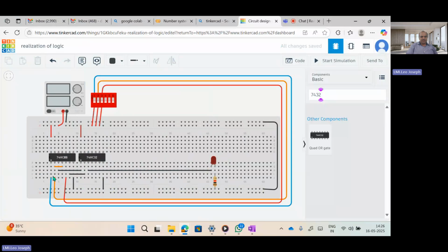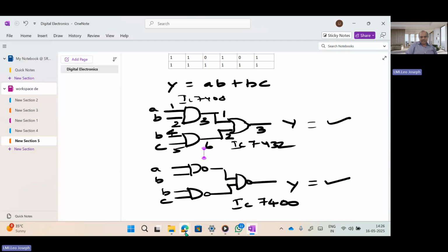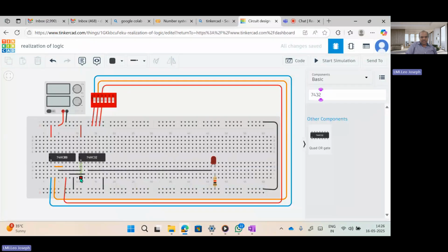First pin, second and fourth shorted. Fifth pin is direct input. And then from here third to first pin, and then from fourth to here. You can check the sixth pin to second pin. So sixth pin to second pin, 4 5 6, this is the sixth pin, and from the third pin I am having direct output to the LED.